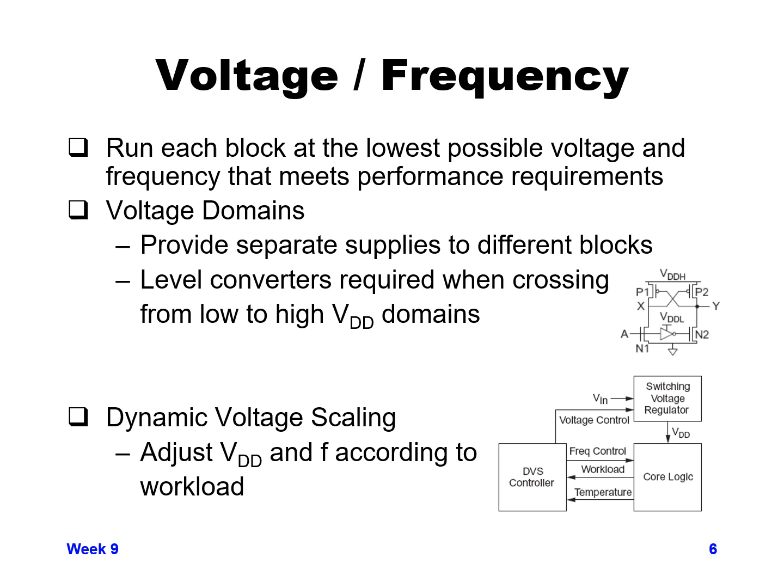And last but not least, definitely not least, as far as trying to reduce your dynamic power, is modifying voltage and frequency. If we can reduce our voltage, like I said before, voltage is a square law effect on your power, so reducing voltage can have a dramatic reduction in your power. But of course, reducing your voltage will reduce the drive strength of your transistors and in effect reduce the maximum frequency that you can operate at. So generally, reducing your voltage requires you to reduce your frequency as well.